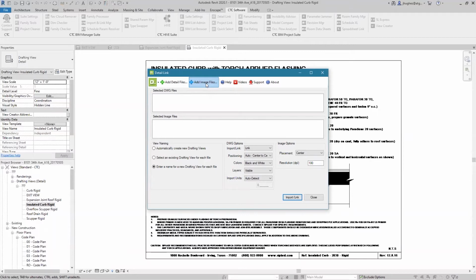It's great to just show up on site with your smartphone and take a bajillion pictures, or punch lists, to take a whole bunch of pictures of existing conditions. And then you can bring those image files into Revit, throw them on a drafting view, and then use Revit's great markup tools on top of it with their text work and dimensions and such, and point to all the work, or use, you know, kind of homemade keynotes or annotations to point to all of the work. Saves so much time over drawing up conditions.